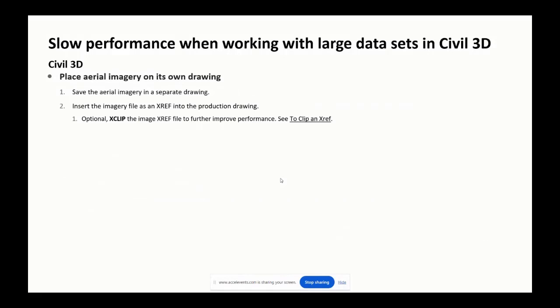We all probably work with images, big images, especially as a lot of us here deal with drone data, and those images get quite large. I find it a lot easier instead of map inserting that or through the task pane into my drawing to have the image drawing as its own DWG. I find it way easier, way better on my files.